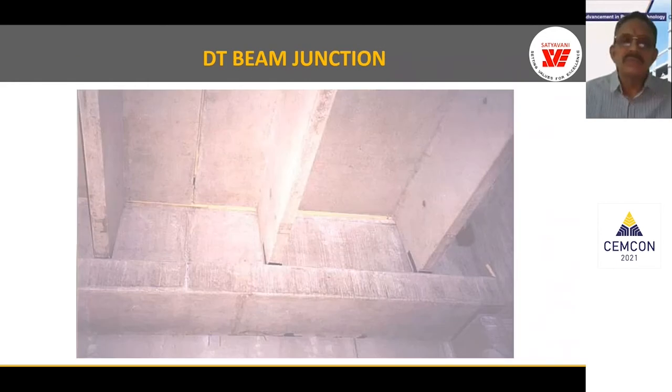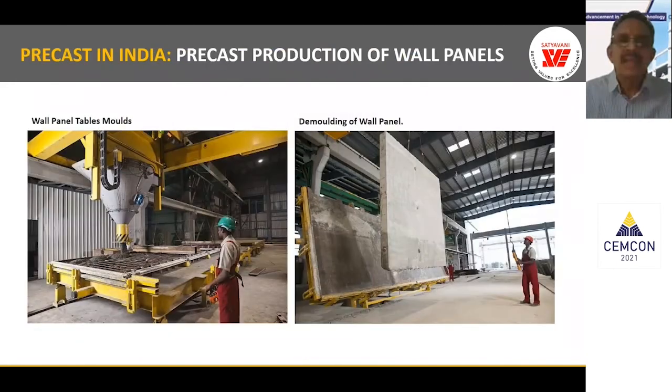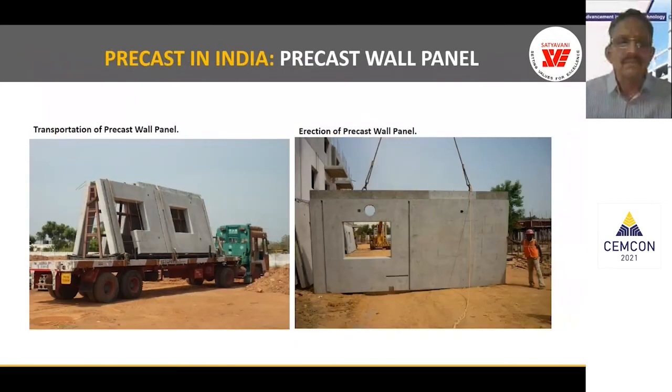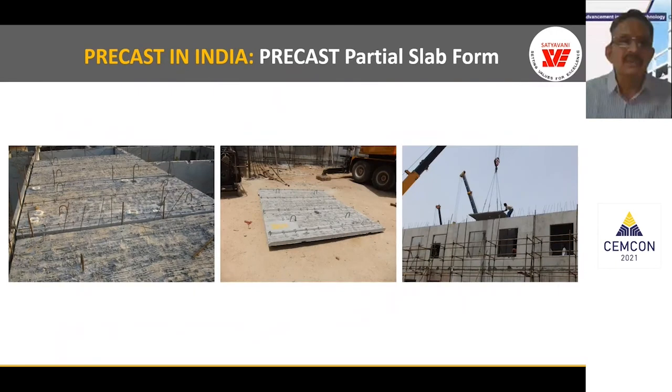So these are also some of the junction details and multi-level parking garages. And these are some of the demolding of the wall panels, which is the simplest technology. We can even set up this casting of the wall panels at the site itself, depending on the time availability and the number of panels to be cast every day. And transportation of the panels and erection of the panels. And this is the precast wall panel erection typical photograph.